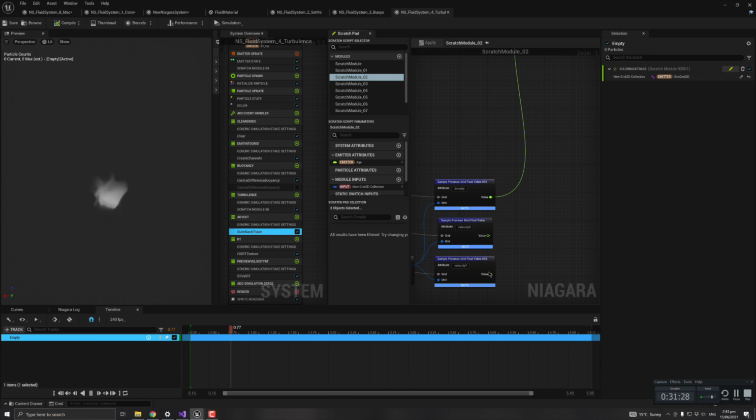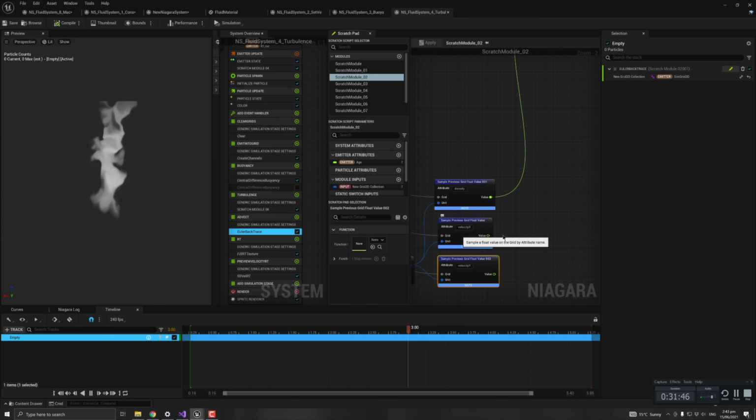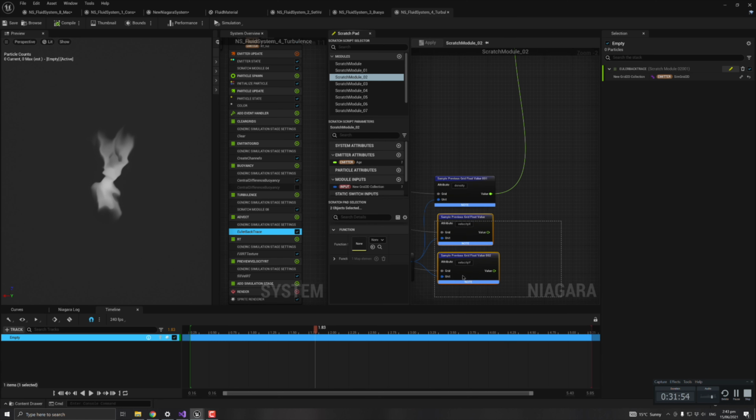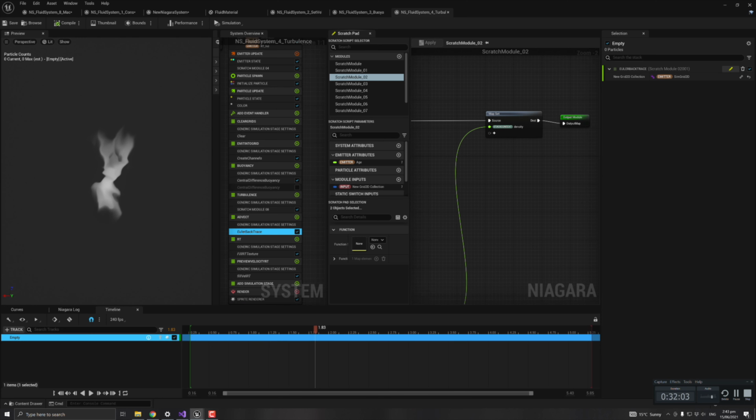And in this case, I'm not actually advecting velocity yet, because when we're not doing a physical solve, these kind of things again can get you most of the way. You don't need to do an actual self-advection of velocity. If you do advect velocity itself, which is a bit weird because you're advecting velocity with the velocity, unless you do something to correct for that sort of fluid mechanical approach, then you're going to end up with a real messy velocity field that you can't use the next frame. So sometimes it's just good to explicitly set the velocity each frame and then just use it rather than self-advect.